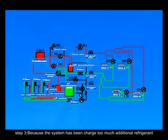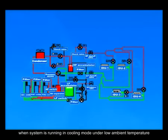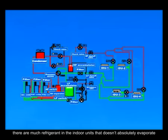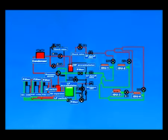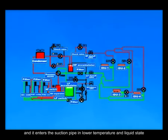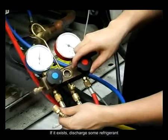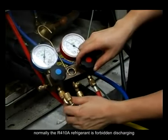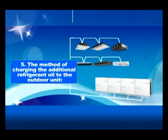Step 3. Because the system has been charged too much additional refrigerant, when the system is running in cooling mode under low ambient temperature, there is much refrigerant in the indoor units that doesn't completely evaporate, and it enters the suction pipe in low temperature and liquid state. If this happens, discharge some refrigerant. Normally, discharging R410A refrigerant is forbidden.